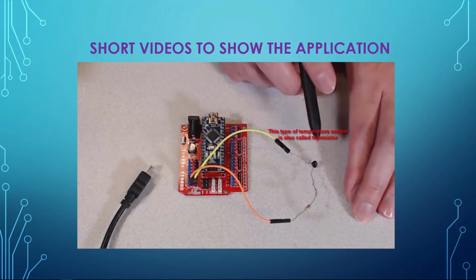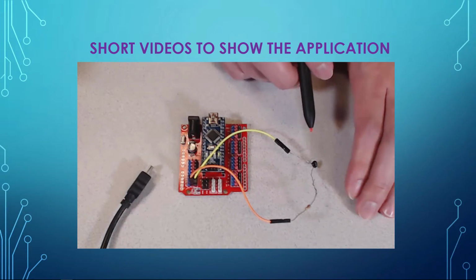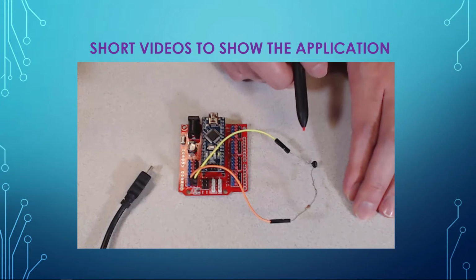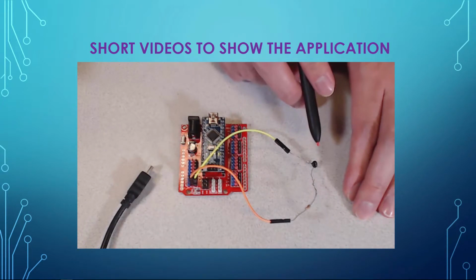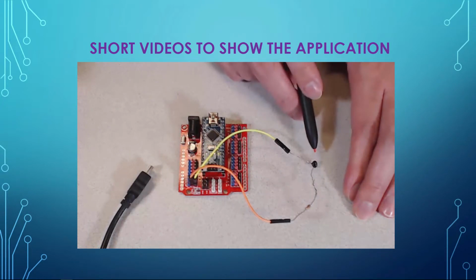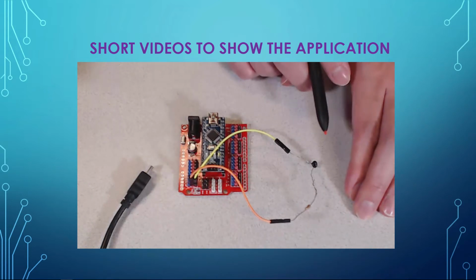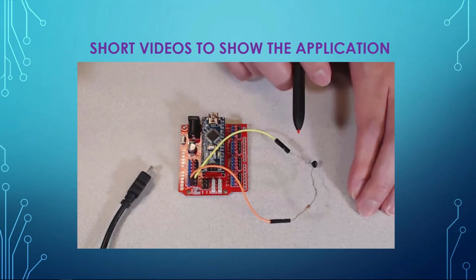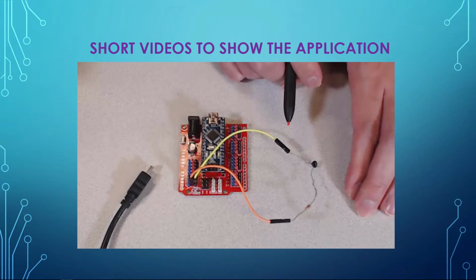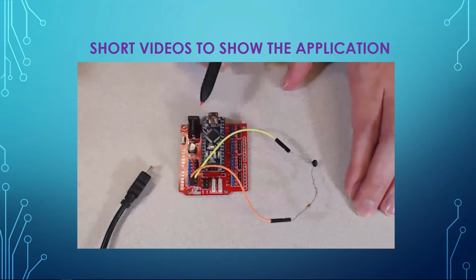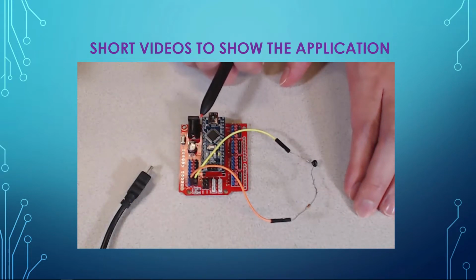It is in fact just a resistor, but the big difference with it is that its resistance changes based on the surrounding temperature. This particular sensor has an inverse relationship with temperature, so when the temperature goes up, its resistance will go down. To get a temperature reading from it, we need to make a little circuit and use the Arduino here to process the information.